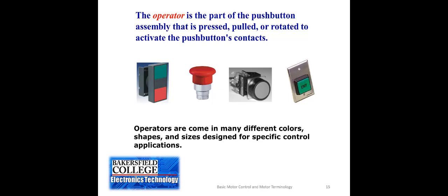We can have regular push buttons like the third one from the left. Sometimes we can buy those with the head of the push button recessed back so that there is no chance for somebody to accidentally come in contact with it. Sometimes we can get those with the head sticking out further, like for a stop button where you want easier access to be able to stop it quickly in an emergency.